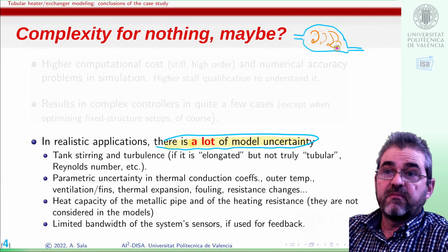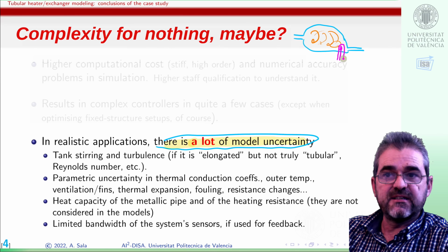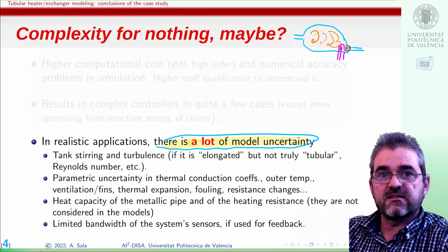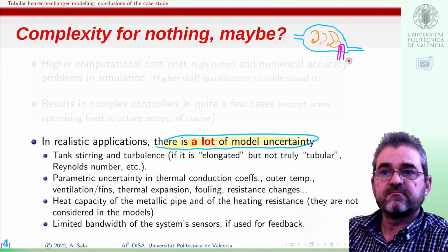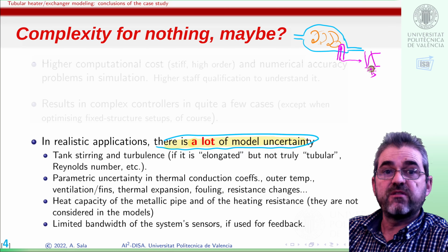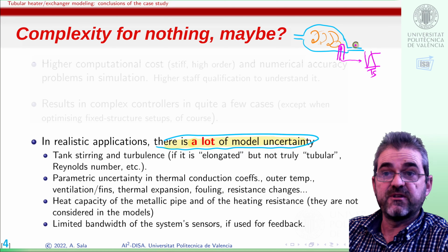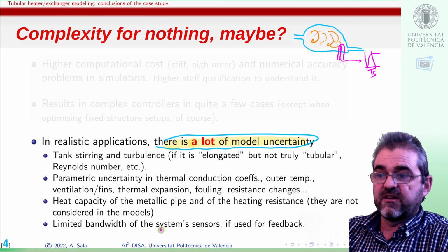And we also may have a thermocouple, maybe protected with some coating, if this liquid is, let's say, a corrosive acid. So maybe the time it takes for this sensor to get an accurate temperature reading, this sensor bandwidth, is of the order of the residence time of the fluid here. So this is another difficulty.